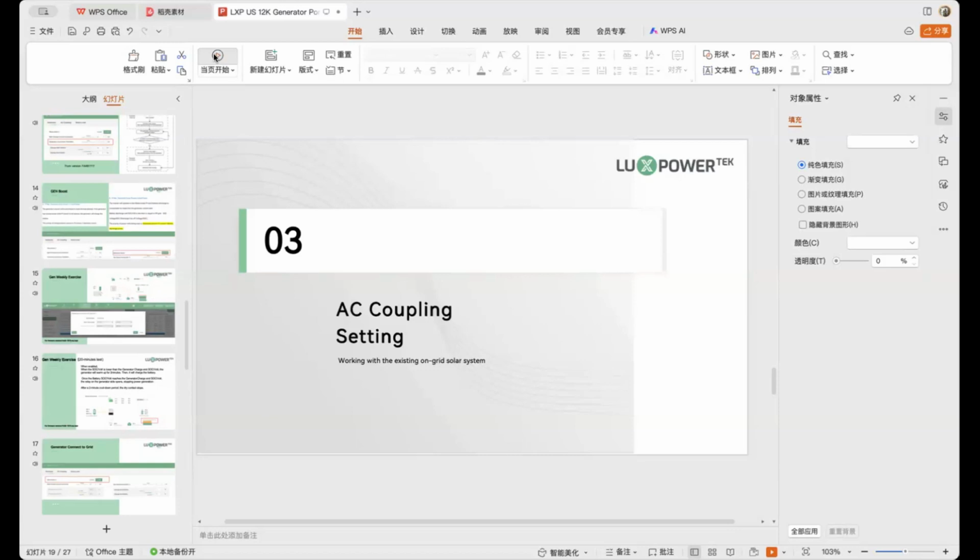The battery can accept a 5 kilowatt charge power. However, if the battery is full, then there is extra power from the PV, right? Then we will shift the frequency to make less power from the AC coupling system. Then the whole system can get a balance. So this is on-grid, the AC coupling like on-grid. This is an on-grid application. Then it's easy. If you have more power, you can feed into the grid.